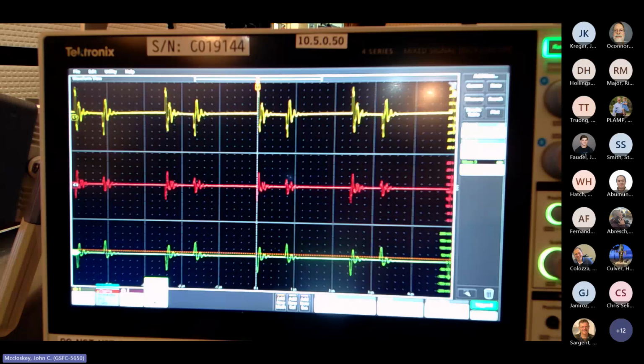Also, it'll be much quicker. I've set the dwell to 100 milliseconds, so it'll be 10 times faster. Going from 10 kilohertz to 200 megahertz with 1 second dwell time and 2% step size takes about 8.5 minutes. So it'll take about a tenth of that amount of time, a little less than a minute. So that's a little more palatable for a demonstration.